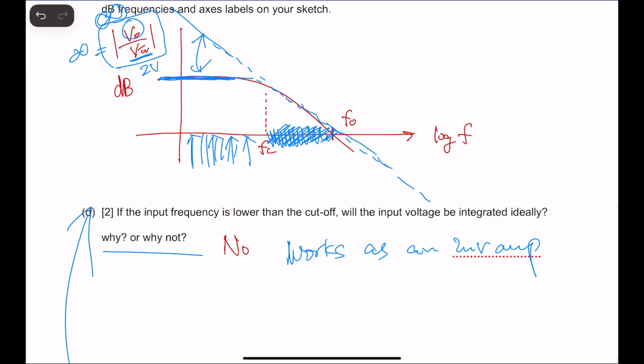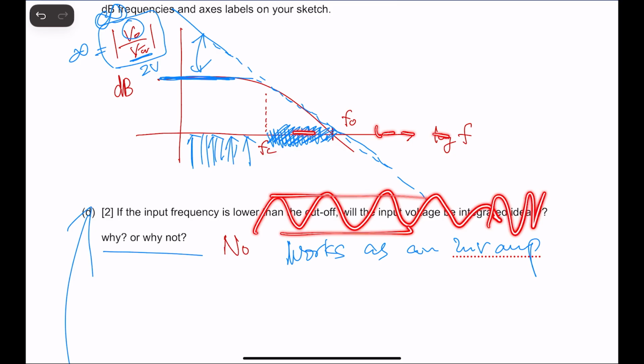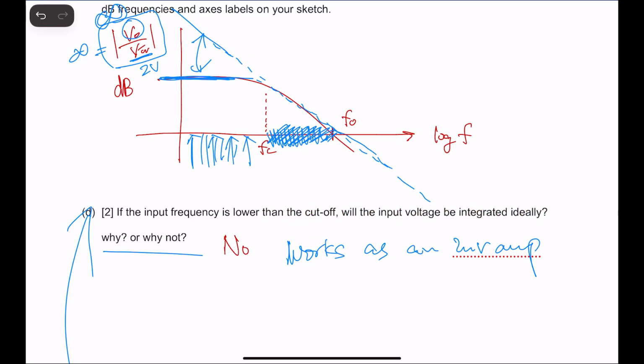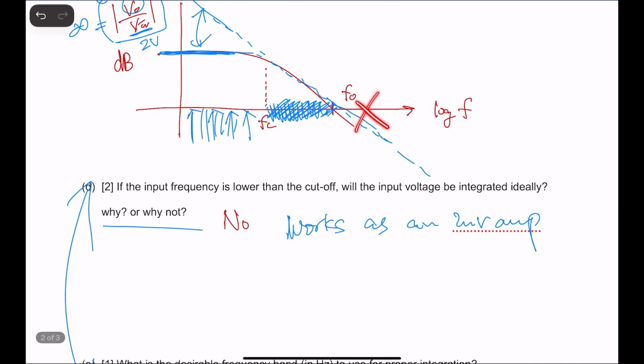You keep the frequency low and measure the amplitude, or you keep it fluctuating faster, or really fast, and then check what the output amplitude is like, and then you find that ratio. And if your input moves too fast, faster than this rate, then your output is going to be smaller than your input. That's this 0 decibel frequency, right? So we don't want to use this range. We want to use this range.